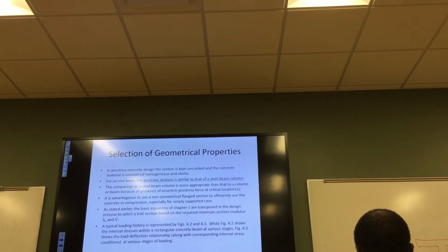So if the neutral axis is here, which is typically what happens, then the concrete below the neutral axis is in tension. So whether it is there or not doesn't matter. All you care is whether you were able to put these rebars and connect them to this compression, right?